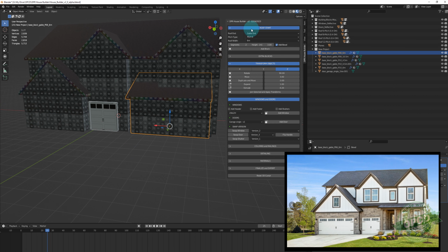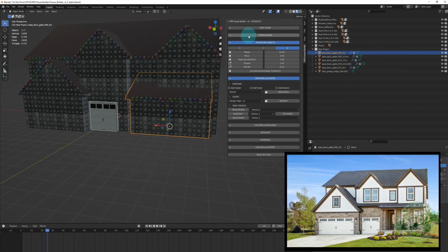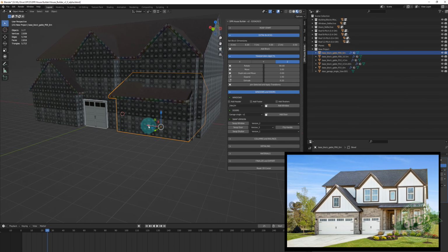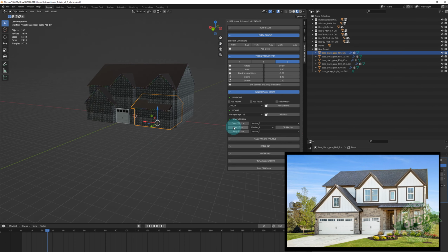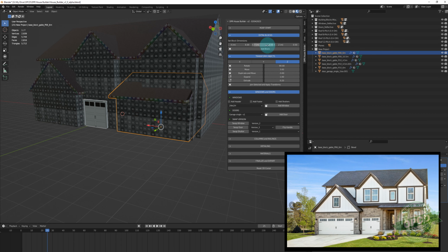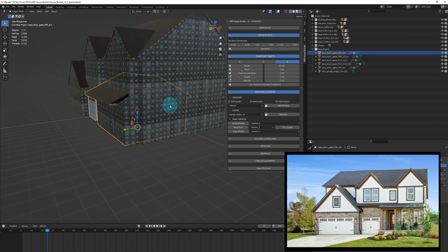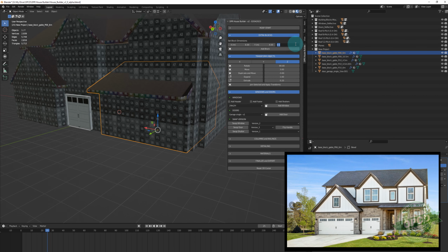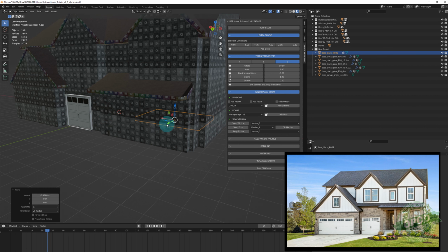That's going to be in the extra block section. So I'm going to close down that roof start section, extra blocks here. It's going to be 6 meters in the X direction. Remember, X is red. I make it 4 meters front to back. That's fine. And then let's make it, probably a half meter tall is okay. Let's try 0.3 meters. Let's add that block, and then let's drag it out here.